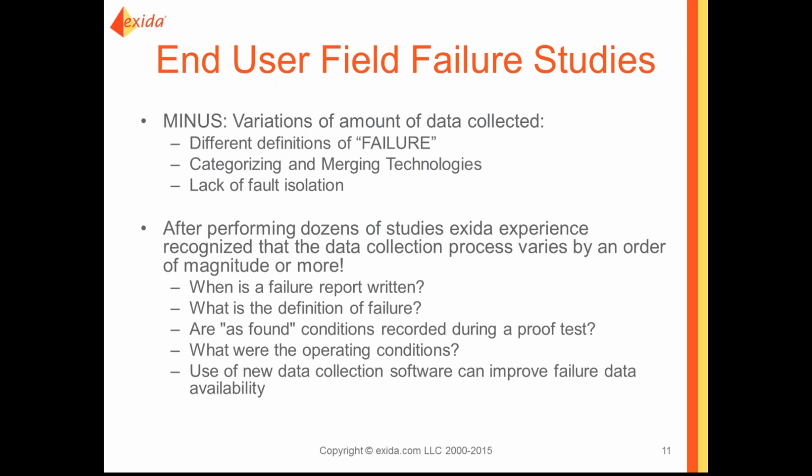From performing dozens of these and looking at studies done by other companies, some of the key things we've identified are to understand when a failure report is written and what triggers a failure in the plant. If somebody just goes out and changes out an instrument and doesn't record it, that may never get into the database. So there has to be some controls on that.